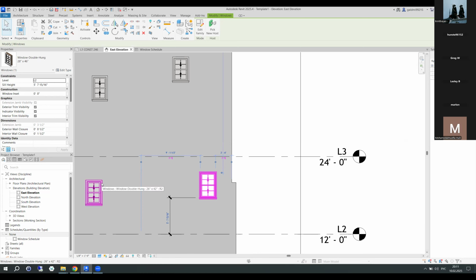Click on another window, right? That's on level 1, right? So just understanding where those are, what controls that, because right now you could change that temporary dimension, or you could put a dimension on it, but it's still reporting to level 1 because that's where it's scheduled, right? So that's why all of your windows say they're scheduled to level 1.